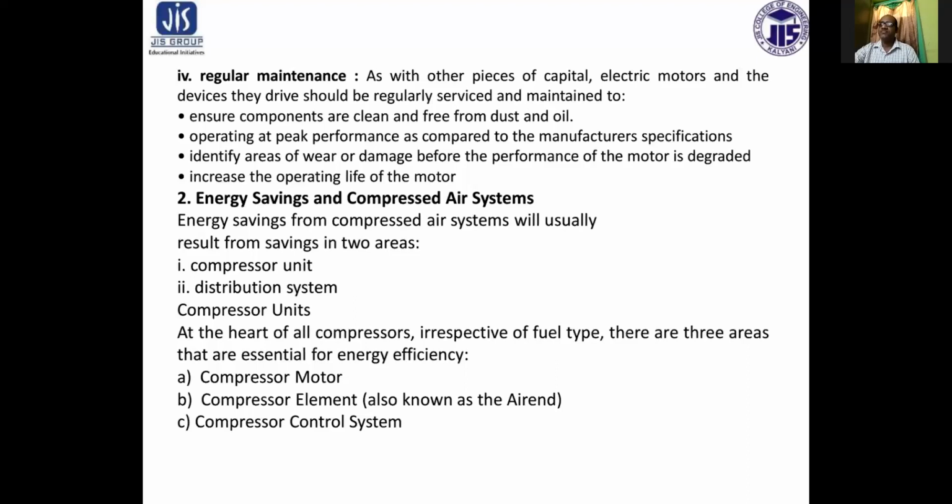Compressor elements. The air end of the compressor is the component that is responsible for compressing the air in the compressor unit. The performance of the compressor element will depend largely on the type of element of the unit, that is, whether it is a rotary screw type, a rotary vane type, or a reciprocating or centrifugal type of compressor, and it may vary by as much as 20% between the styles.